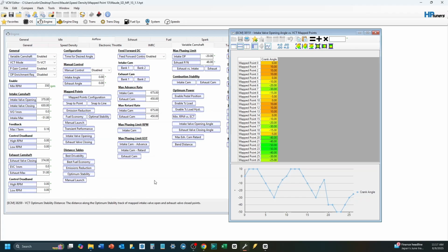So having done the MAF, right, then we go ahead and do all the speed density tables using the pressure sensors, and then we'll put those all together with the blended math and rip a couple logs, and you should see that the fuel trims against the pressure points and the fuel trims against the airflow points should all be in line. I like to shoot within 2%. Within 5 is more than acceptable, but I really like to get it locked in because, of course, once you get into the world of power enrichment,